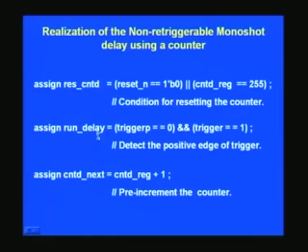And in this one we have noticed that the input is trigger, and we want to sense the rising edge of the trigger as such. How do we sense? One way is to put always at positive edge clock, but there you can't have more number of clocks. In any system you need to restrict it to say 2 or 3 clocks, and not cross that number. So what do we do if you have so many other signals which also need to be sensed at the rising edge, or for that matter the falling edge?